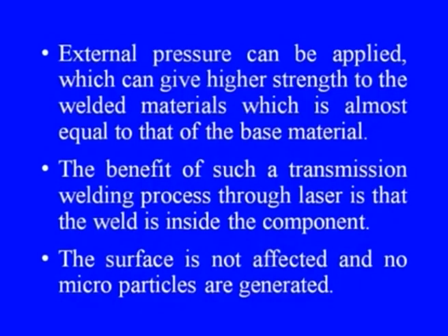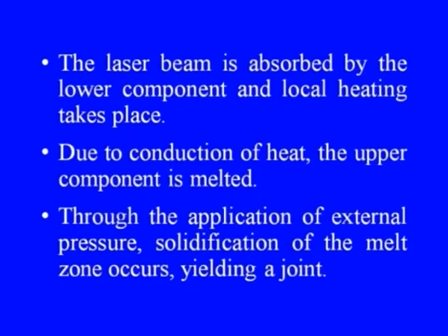External pressure can be applied to make them get intimate, which can give higher strength to the welded materials, which is almost equal to that of the base material. The benefit of such a transmission welding process through laser is that the weld is inside the component. This is very important, that it is not exposed to the environment. The surface is not affected and no microparticles are generated in the joint.